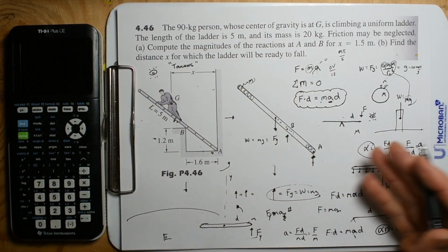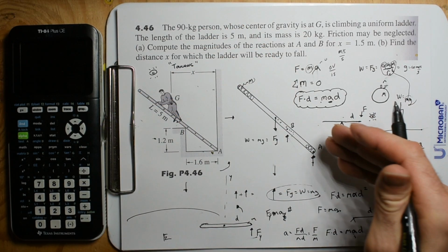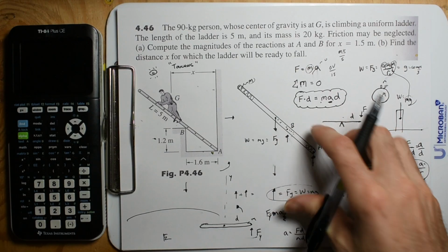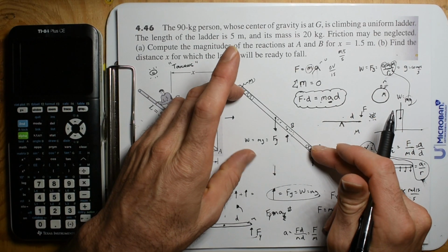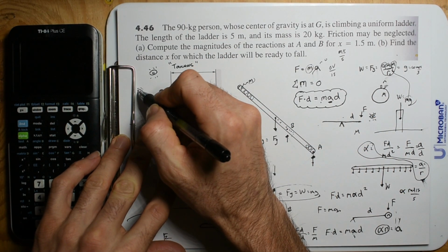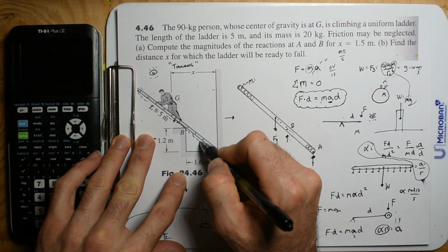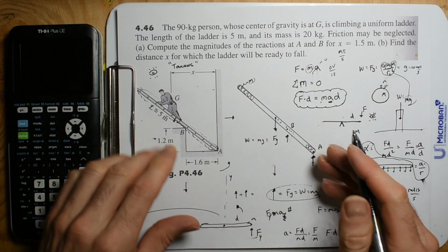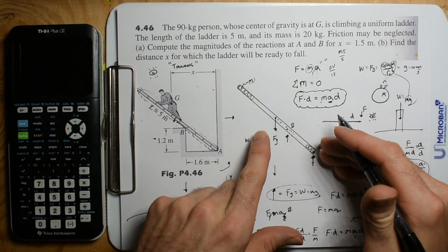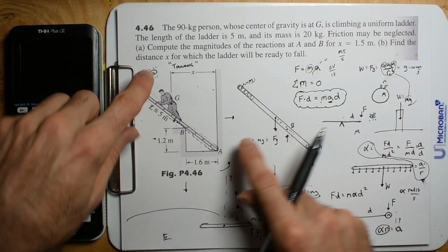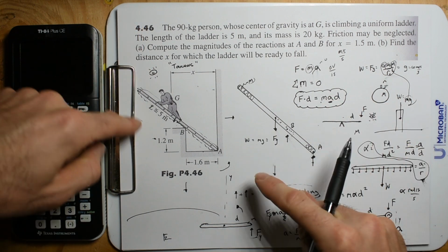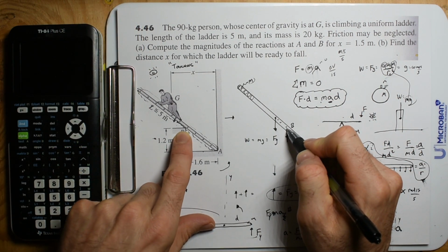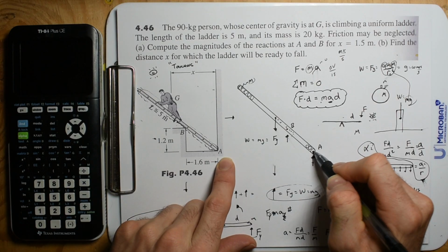I'm trying to just develop a style where you can easily tackle a free body diagram. One, get the thing in outer space, and I guess I didn't do this, but you really want to chop it out of the problem. So I'm just going to chop that whole thing out. And now we come to the other part that's useful: is this ladder touching anything on Earth? And you're like, oh, yeah, it is. It's touching something at B, and it's touching something at A.